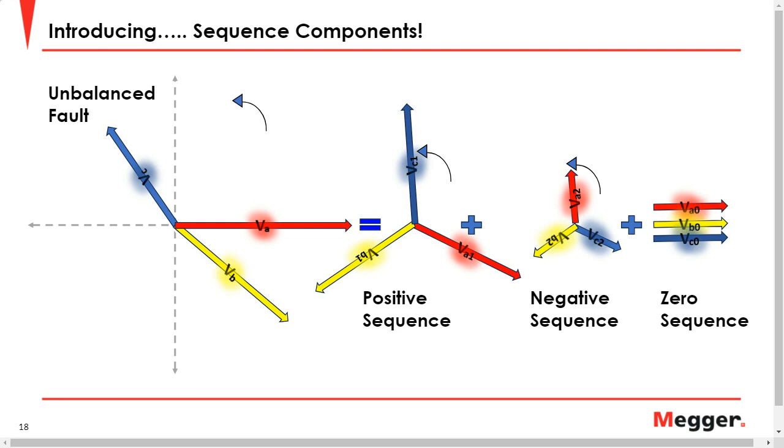But in the case of the negative sequence component, if the feeder feeds mainly motors, you have to be very concerned with whatever amount of negative sequence you have there, because of what Mike explained in the presentation, where he showed the effects of negative sequence components on induction motors.